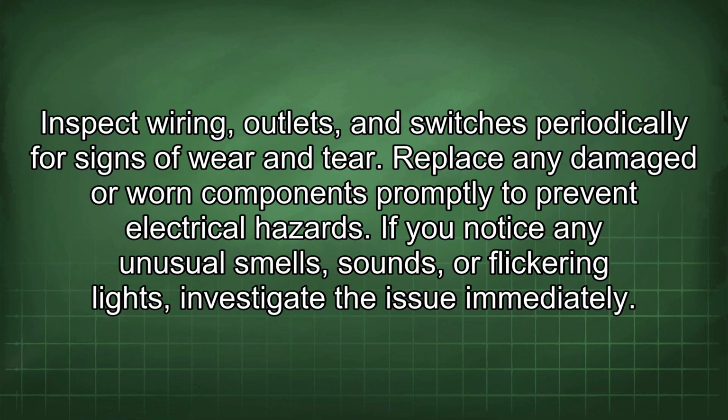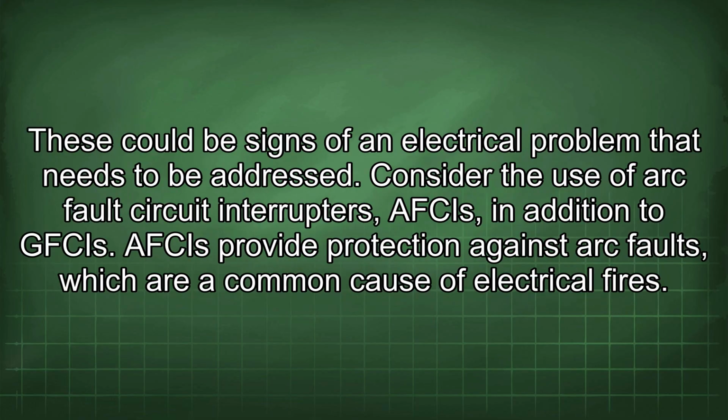Inspect wiring, outlets, and switches periodically for signs of wear and tear. Replace any damaged or worn components promptly to prevent electrical hazards. If you notice any unusual smells, sounds, or flickering lights, investigate the issue immediately. These could be signs of an electrical problem that needs to be addressed.